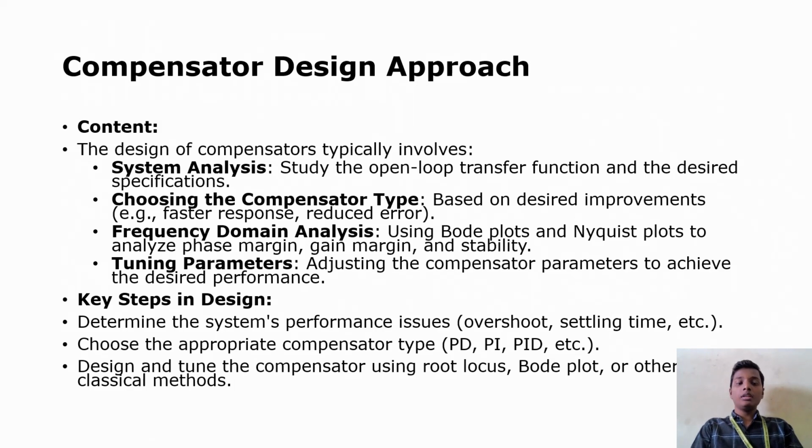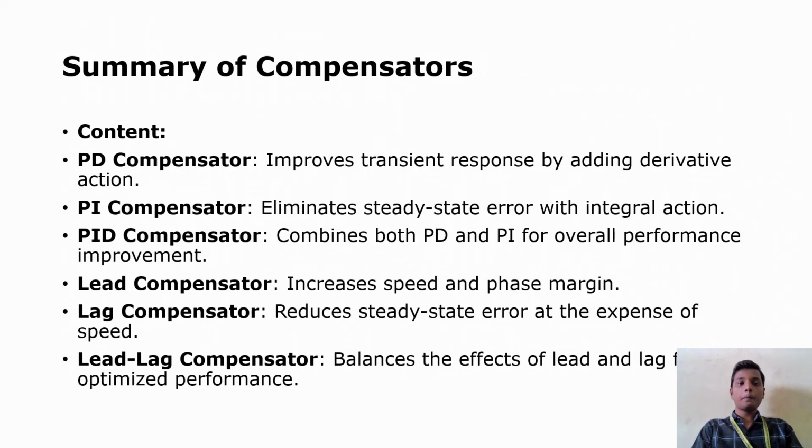Key steps in designing. Determine the system performance issues like overshoot, settling time, etc. Choose the appropriate compensator like PD, PI, PID, etc. Design and tune the compensator using root locus, Bode plot or other classical methods.